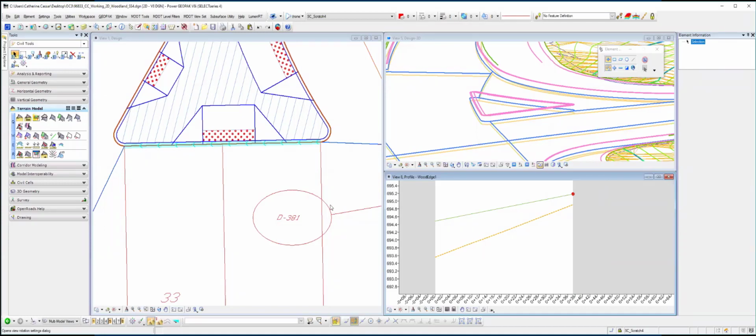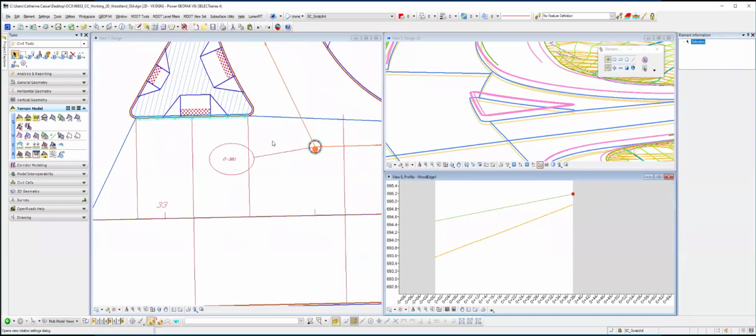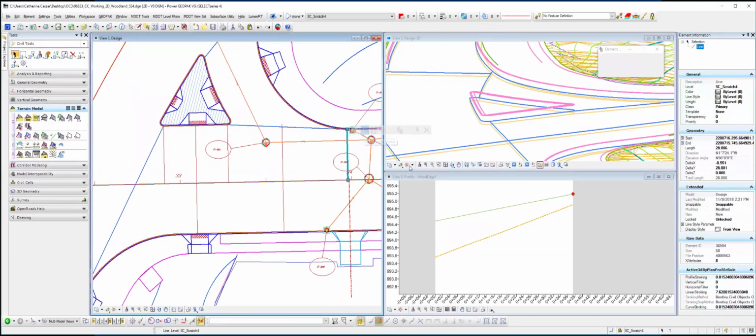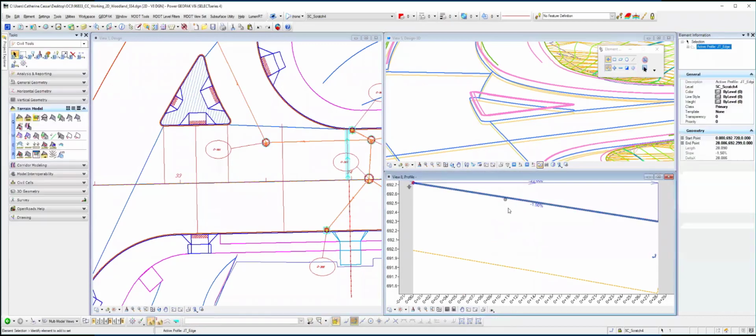They're just control lines. So then I was at 1.65, and then I was trying to get myself back down, and I had to use essentially the rate of super, and I calculated what I needed to be, because I had to be back over here, sloping back in this direction, so that the vehicles, as they came through this auxiliary lane, were sloping northward toward that outside edge, right?